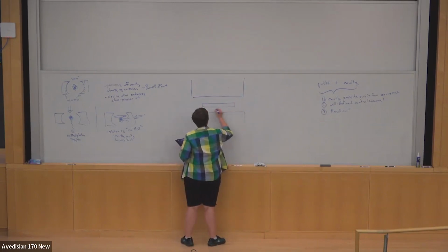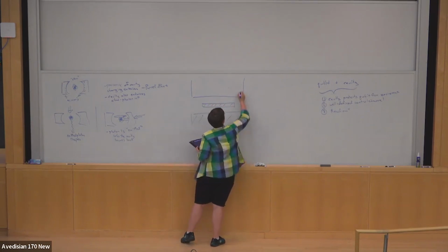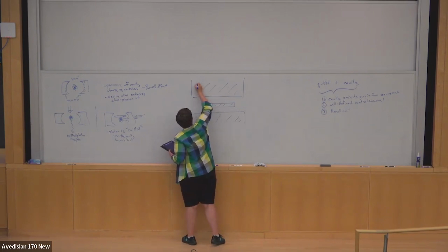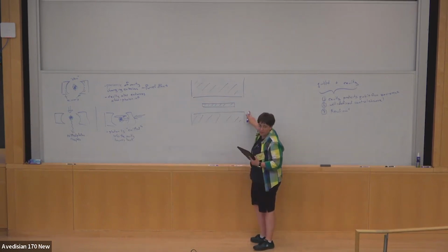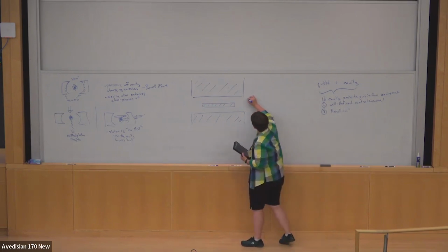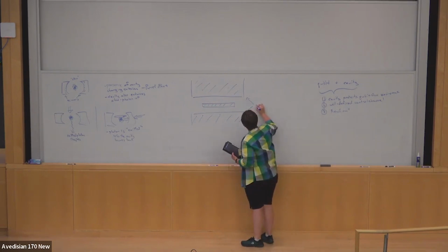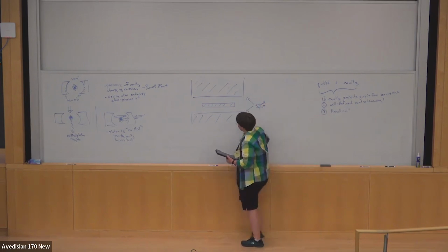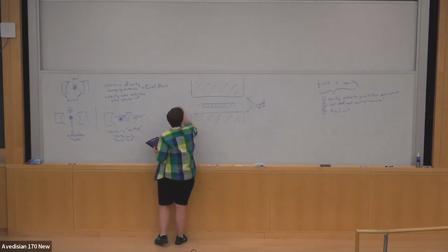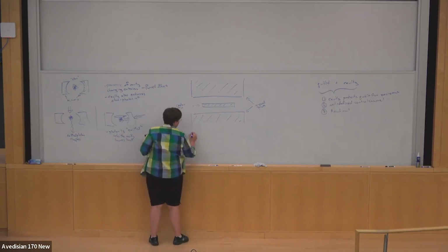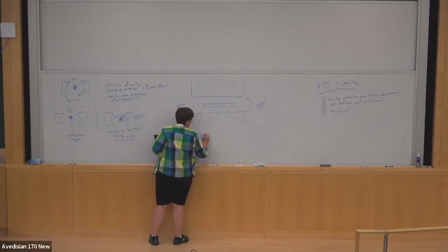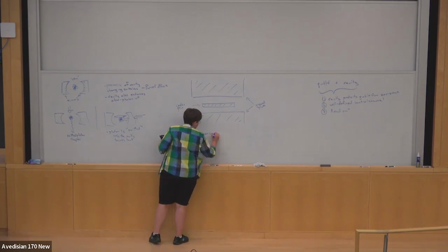So this is a cartoon picture. And so all of the hatched stuff is a superconducting film, and this is sitting on top of a substrate. And so these two pieces here are ground planes. And this little thing in the middle is called the center pin. And this is a coplanar waveguide resonator.